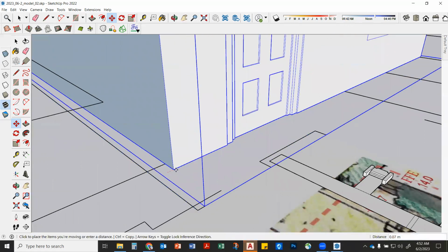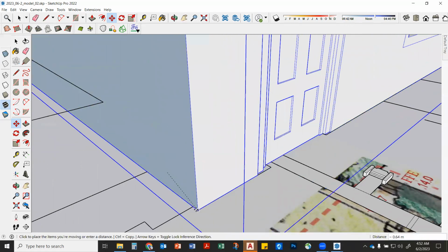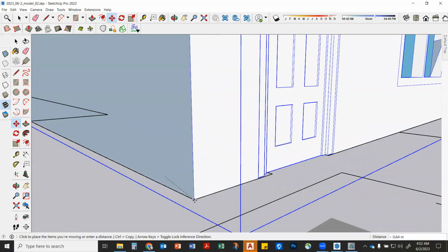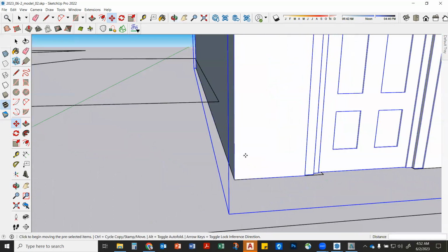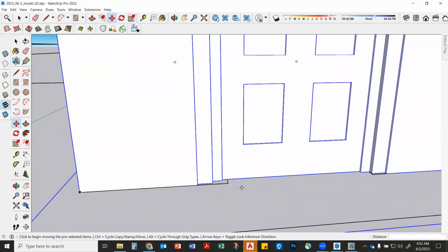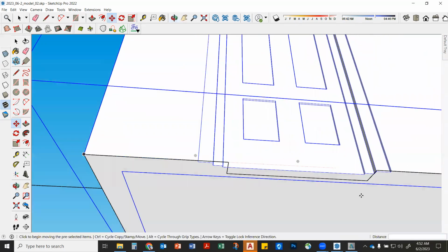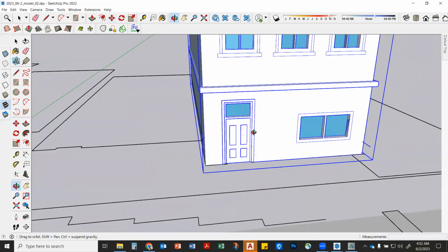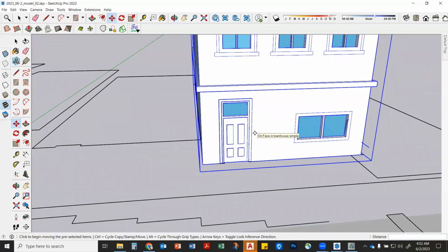So I need it to line up. So I'm going to come over here. I'm going to grab this. I'm going to make sure it lines up right on that corner, okay? See that? Right on the corner of that CAD block. Doesn't really matter which one we start in because it's actually going to copy that. But look, the way you know it's lined up well is that the door should line up pretty close. I kind of made it close. It's a little bit off, but for this example, it's perfect, right? Now watch this. Now we're going to go Control X, which is what? Cut.